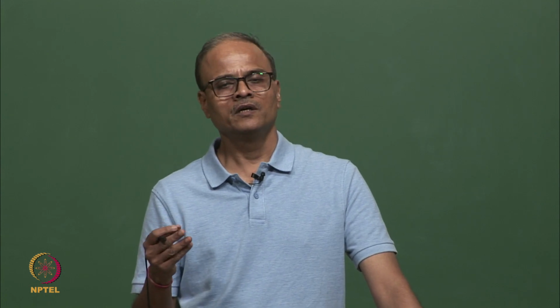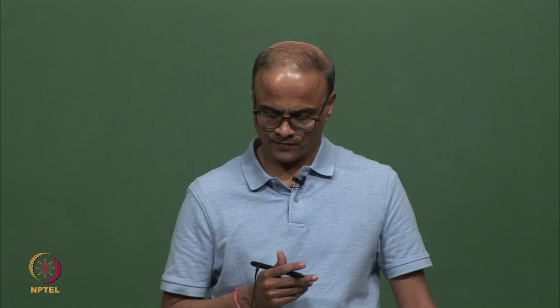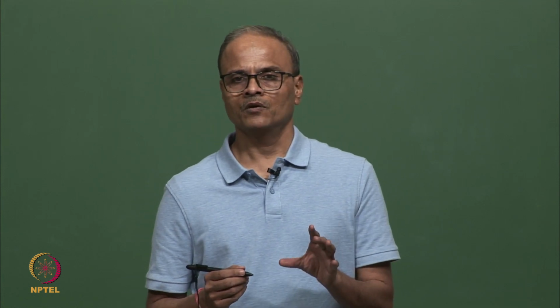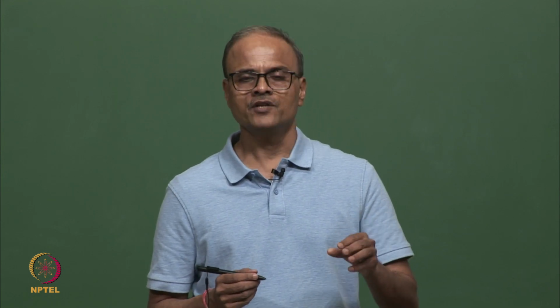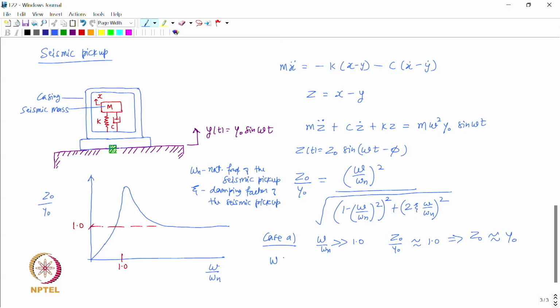That would be the estimate of the amplitude of the vibrating surface, and therefore this pickup will act like a displacement pickup if we measure the relative displacement of the seismic mass in the range omega upon omega n more than 1. So in the range omega more than omega n, the seismic pickup can be used as a displacement pickup.